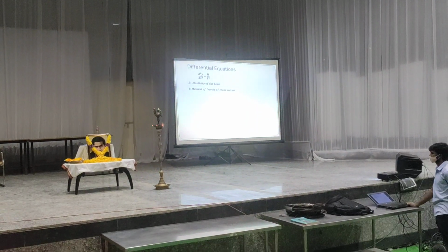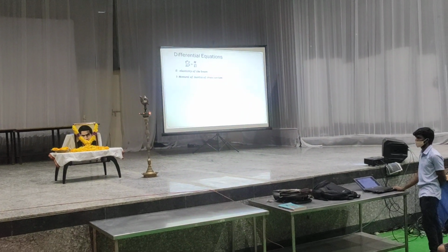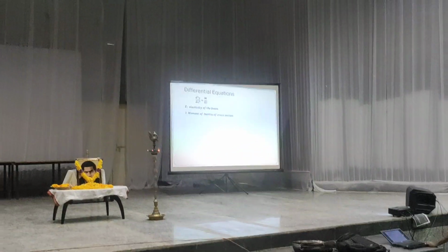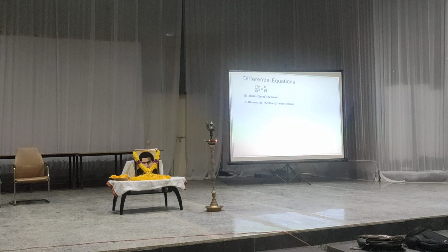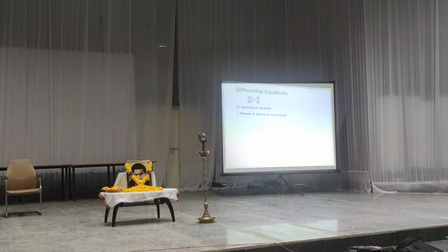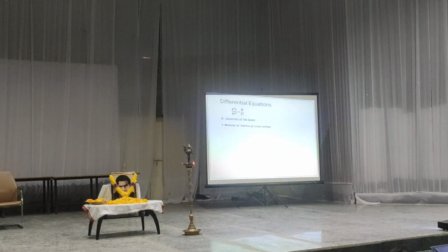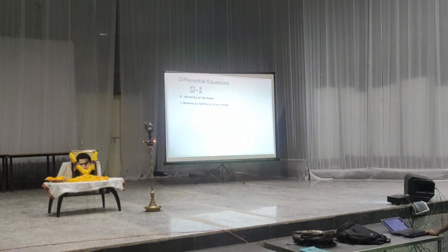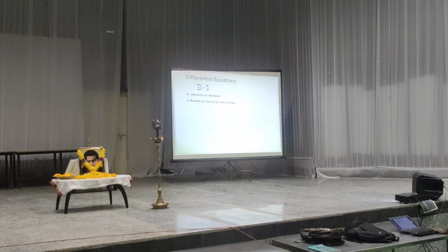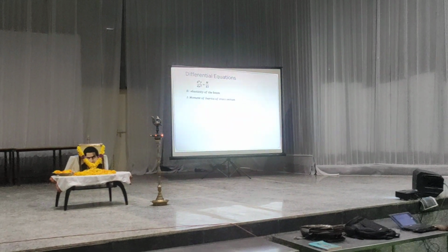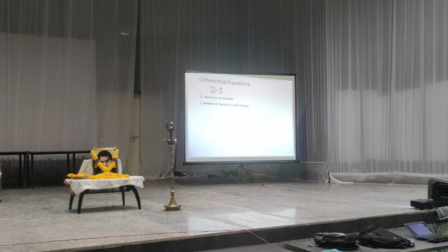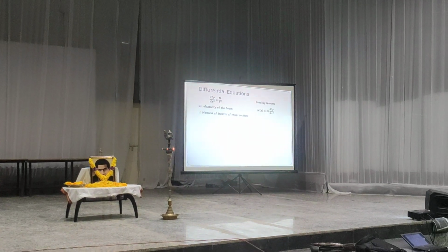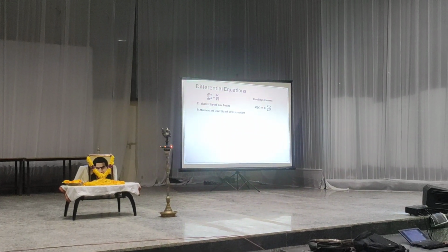And here you can see some differential equations which occur when you study these deflections in beams. So this is one equation which tells about deflection in a beam. You can see that E is the elasticity of the beam. For different materials, you'll have different elasticities. And I is the moment of inertia of the cross section. Of course, to calculate moment of inertia, one needs to use integration. And next, M represents the bending moment. So if you want to calculate the bending moment, that is the equation which gives the bending moment.